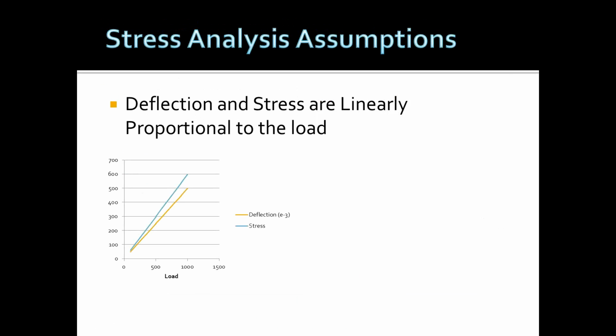If we can all envision a diving board made out of metal. As you apply 500 pounds on the end of that diving board, it deflects downward towards the pool whatever amount. As you apply 1,000 pounds, it deflects more. 1,500 pounds deflects more. And as you plot those points on a graph, you will get a straight line. That is your linear form. And the reason it's linear is dependent on various things, but mainly is the material that you're working with. So the vast majority of your metals are going to be linear for most of the part.